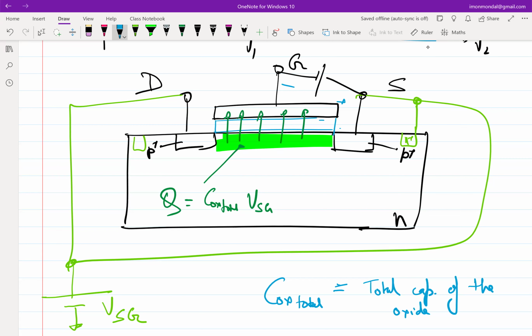Do you recall that? So you had n-type, everywhere we had mobile electrons. We applied some voltage to drive the electrons away. So some voltage was needed to first free off that place. And then you apply some more voltage, and then the holes started to appear. So as long as we know that voltage beyond which the holes start to appear, then we are good. That is a very important quantity, and its name is threshold voltage. Essentially, if we know that below some threshold voltage there are no mobile charges, and above that threshold voltage there are mobile charges,